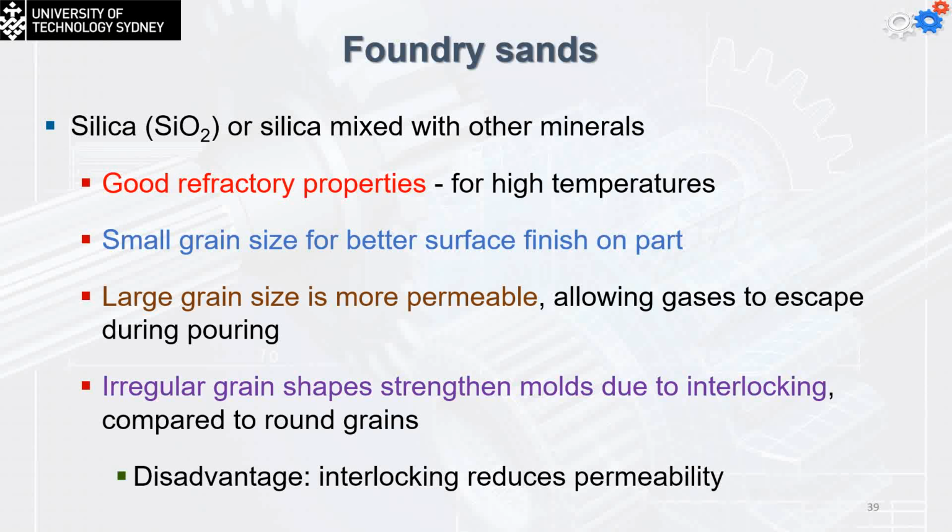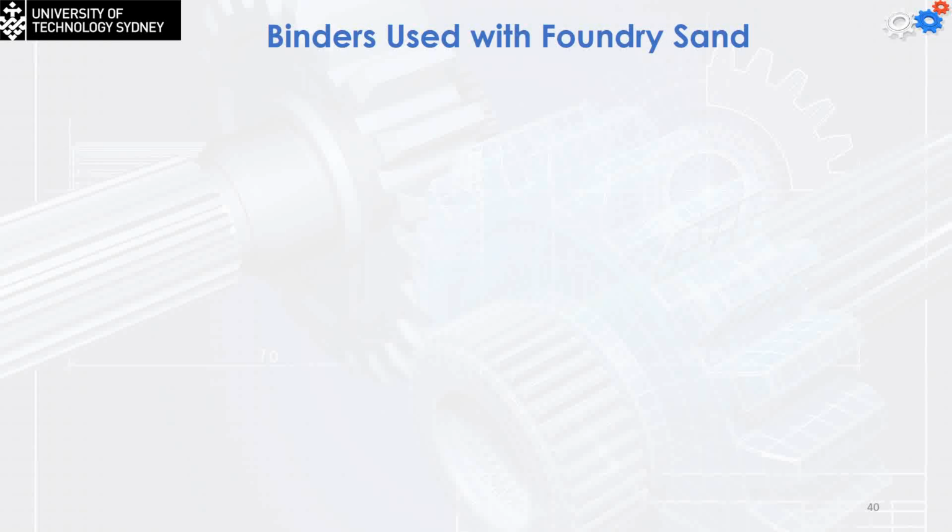Now just remember that you have a box you are going to fill with spherical marbles. They're not going to hold each other, as opposed to a box filled with irregular-shaped particles, because in this case we have what we call the interlock process, where each particle holds the others, so they're not going to have the flowing process. But the problem with irregular grains is that we're going to have reduced permeability, and this is simply going to increase the cooling time for the part.